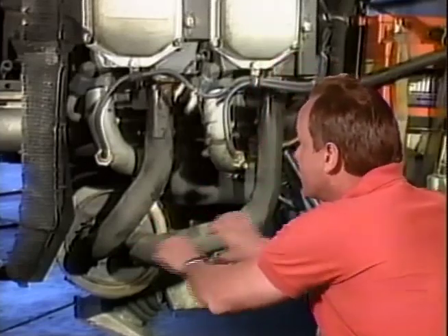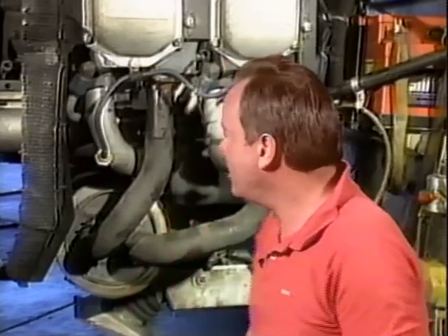Also, you know, there's a lot of expansion and contraction in an exhaust system because it heats up or cools down. So you have slip joints installed very often, and they're required in most exhaust collector systems because of expansion and contracting caused by high heat and cooling. So very often you'll have slip joints. What's the purpose of a slip joint in an exhaust collector ring? Well, it aids in alignment and absorbs expansion. That makes a lot of sense.